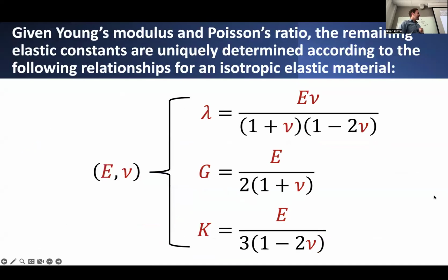Kind of interesting. I will say, though, that as I had mentioned, not all of these different elastic constants that we've discussed are independently defined. In general, if you happen to know 2 of them, let's say if you knew Poisson's ratio and Young's modulus, then there are other expressions that you can derive to determine what these other coefficients need to be in order to satisfy these independently defined relationships.